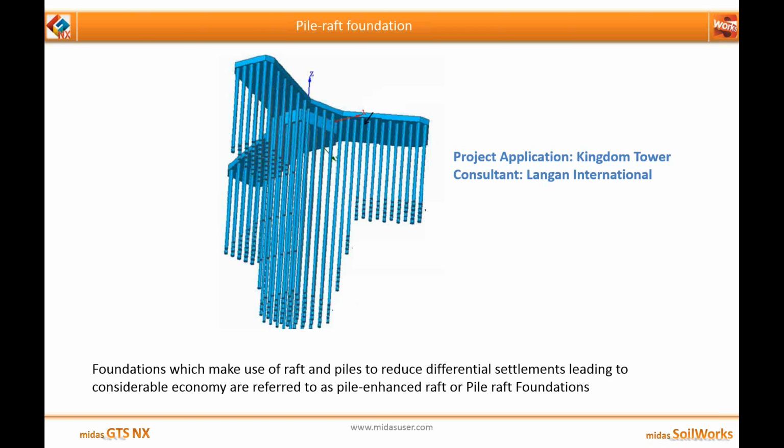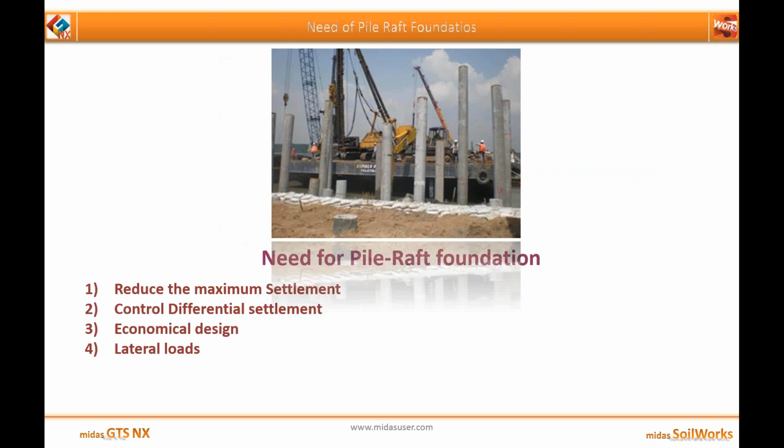So, pile-raft foundation. Foundations which make use of raft and piles to reduce the differential settlements, leading to considerable economy, are referred to as pile-enhanced raft or pile-raft foundations. The need of pile-raft foundation comes into places where you need to reduce the maximum settlement, where you need to control the differential settlement, where one needs to go for an economical design, or where lateral loads play a very important factor.